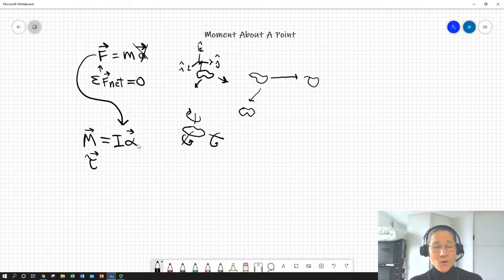If we're in statics, we don't want something accelerating rotationally any more than we want it accelerating translationally. So if you imagine you've got a dam holding back a lot of water, if it twists, it can shift on its abutments and release all the water. And that's kind of what happened with a few of the noteworthy, very deadly dam failures like St. Francis in Los Angeles. So we don't want any translational motion in statics, and we don't want any rotational motion. We don't want any rotational acceleration. Well, we're not going to take the moment of inertia away from our bodies. We're not any more than we're going to take away their mass.